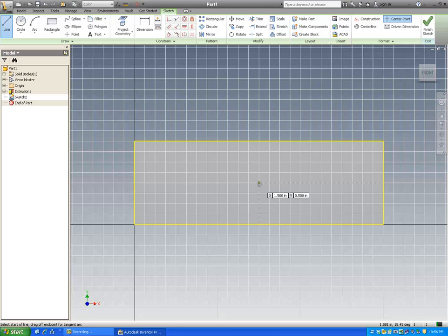And if you notice that we now have a dotted line, so I'm now in the middle of the block this way. Okay, whoops, I forgot to get the line this way, so I get that snap dot. I go up here, it's giving me an angle so I can see I'm at 90 degrees. So I click that. Now escape to get out of that command.